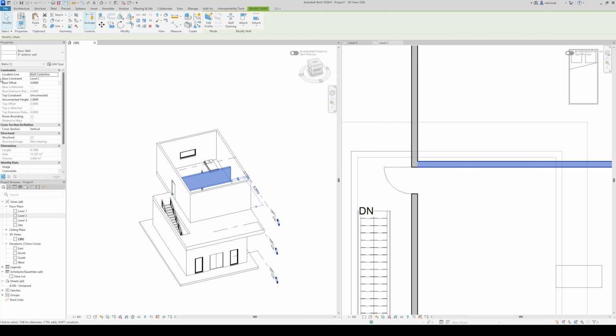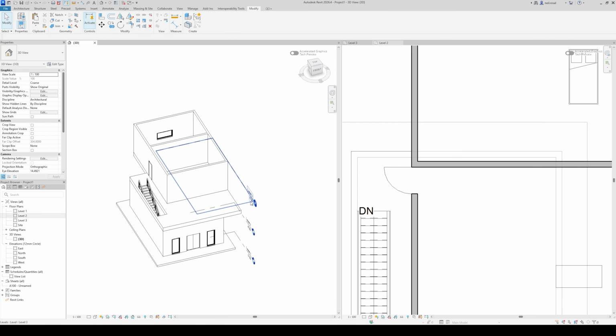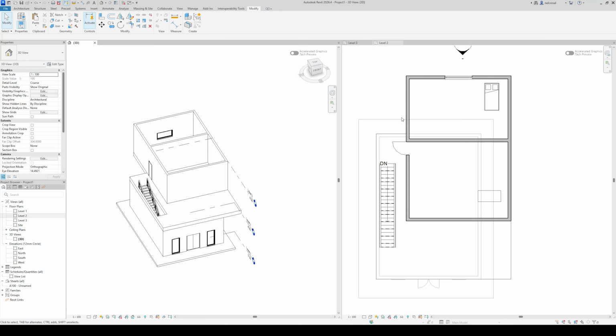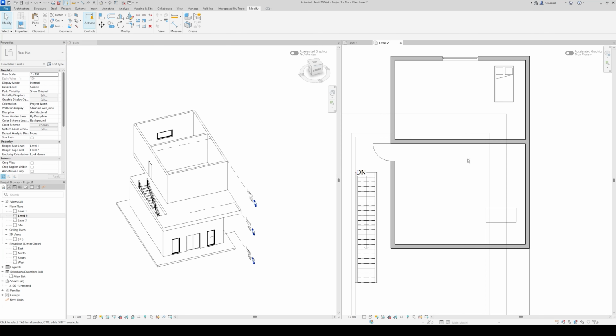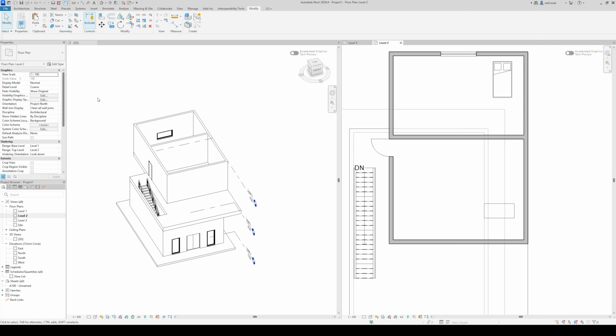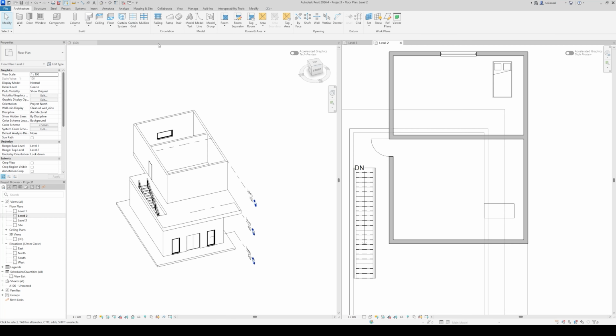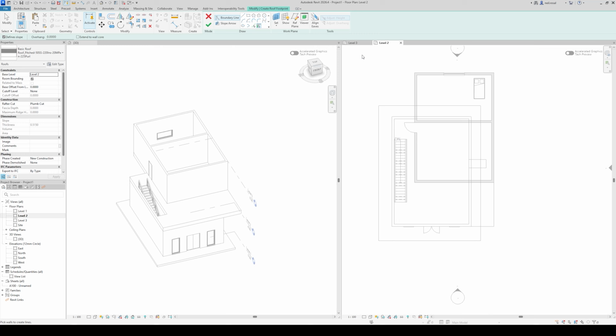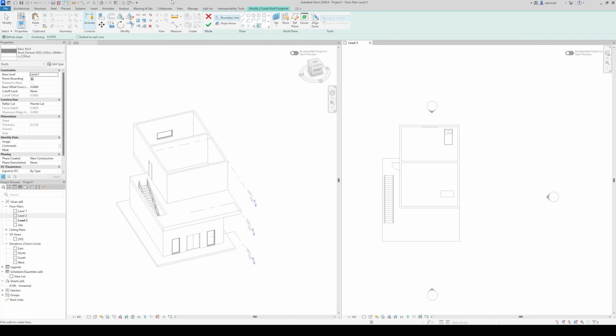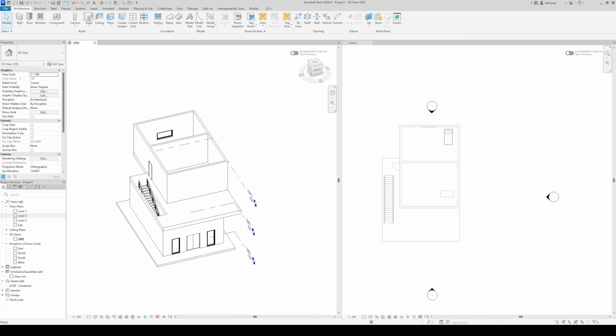I also want to attach this to my level 3 top constraint, and it will automatically go to level 3. I will show you why we want to do that. I'll show you something cool when we create our roof for it. So let's go to our level 3, have our underlay on. We go to create a roof, we go to the Architecture tab, Roof by Footprint.